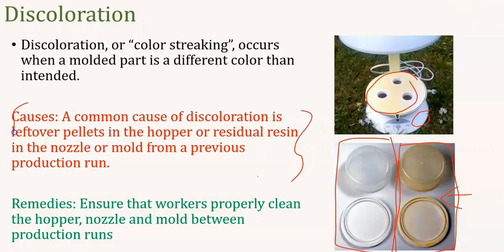That means the complete mold cavity and the hopper have to be cleaned before going to the next process, because the hopper is particularly for injection molding, so this can happen repeatedly there. In injection molding you can use different sets of materials, so before changing the material you have to clean all the parts of the injection molding. By doing that we can reduce it.